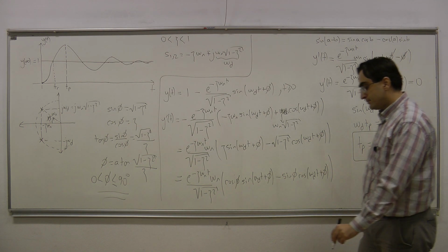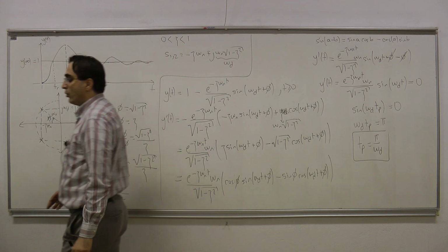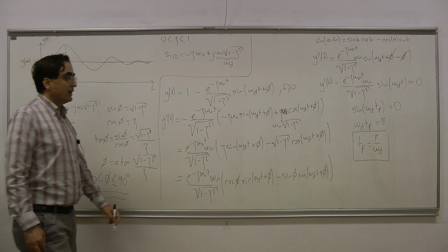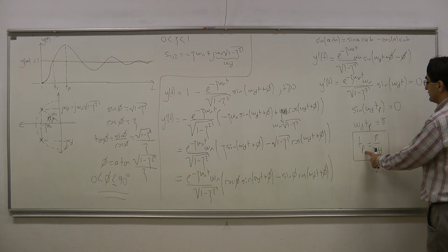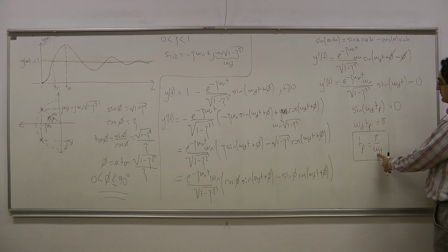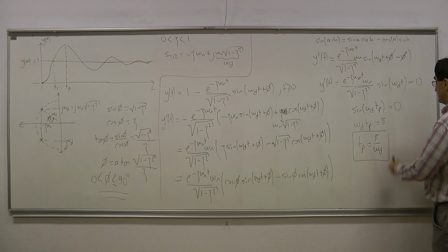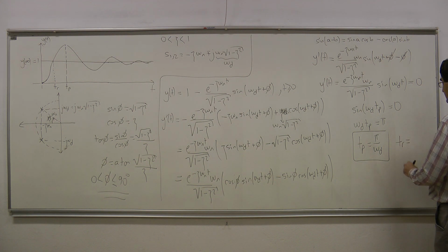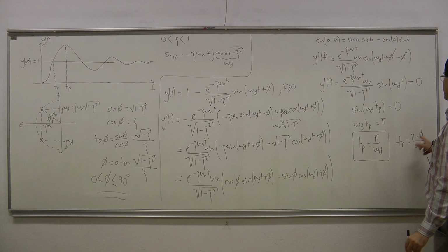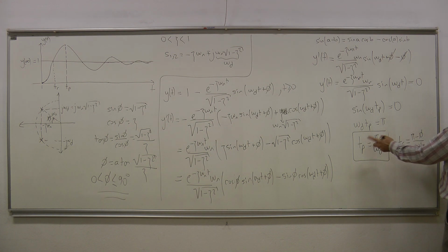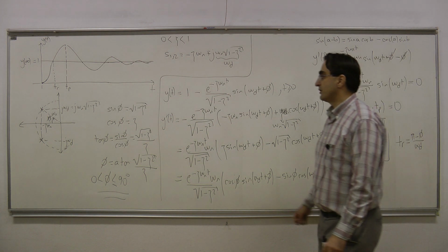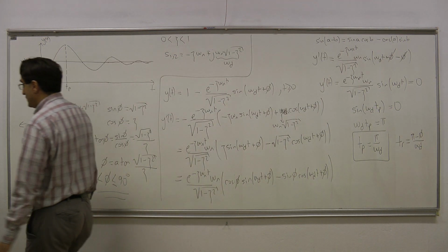That is my formula. That is the time domain analysis formula relating the peak time to the Laplace domain quantity omega d. Compare this with TR, which is pi minus phi over omega d. We see that if phi is non-zero, Tp is always larger than the rise time.